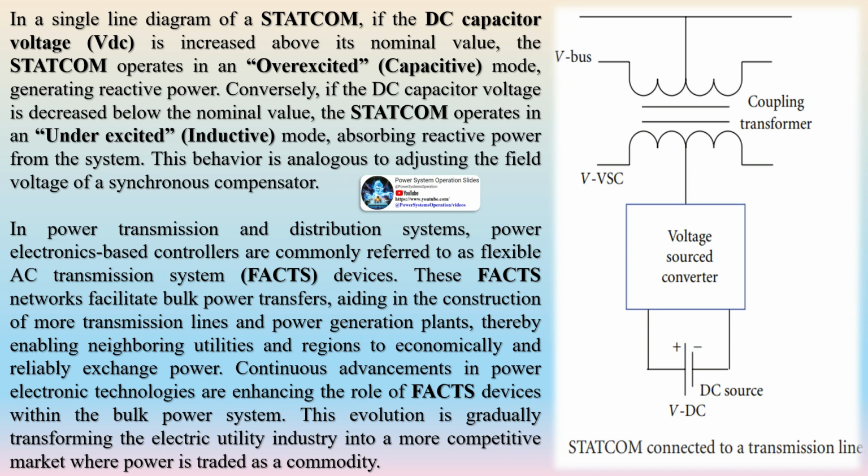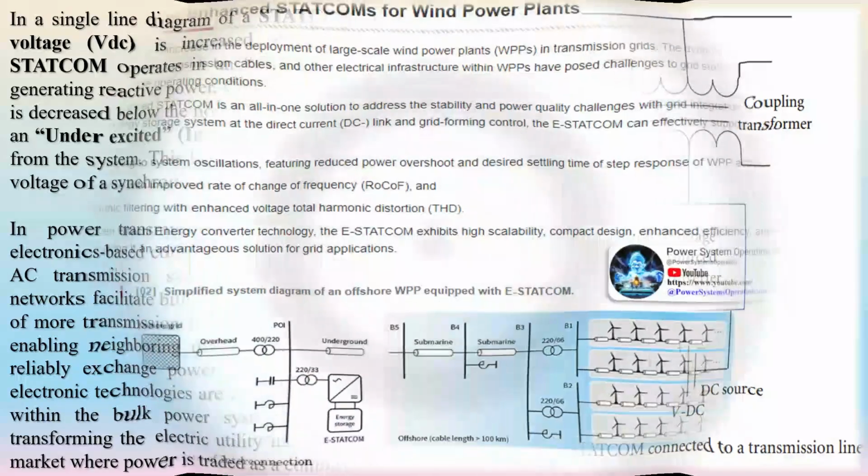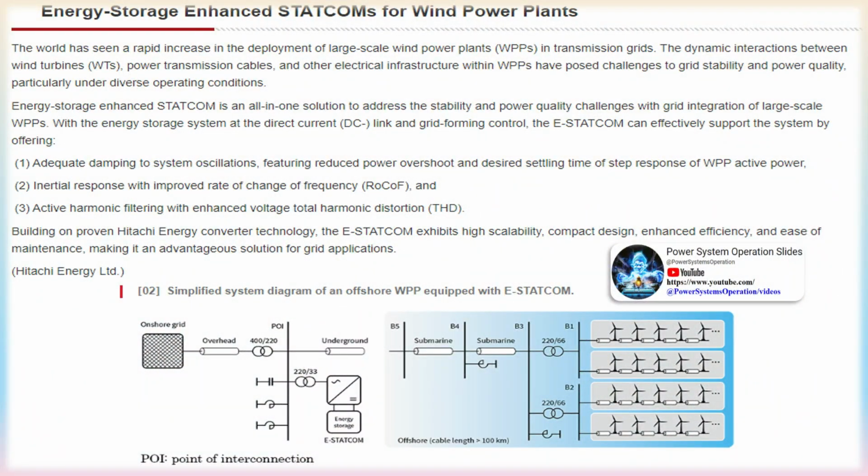An energy storage system (ESS) plays a crucial role in power system control, offering significant enhancements over traditional STATCOM performance. Recently, battery energy storage systems (BESS) combined with STATCOM have emerged as one of the most promising near-term storage technologies for power applications. Integrating an ESS with a STATCOM allows for the control of active power flow between the STATCOM and the point of common coupling (PCC). This enables the STATCOM to not only compensate reactive power but also store excess energy when generated power exceeds the limits that can be injected into the distribution grid.